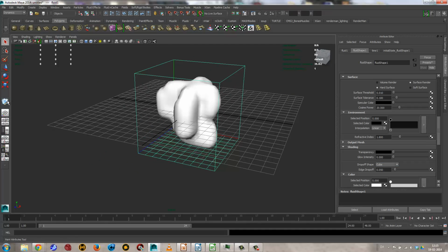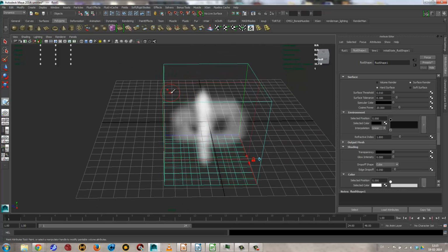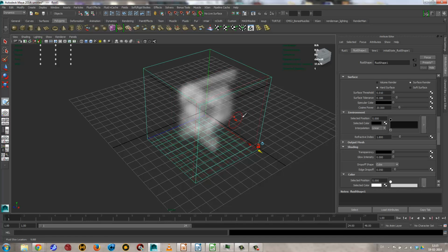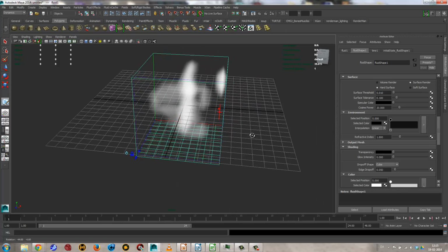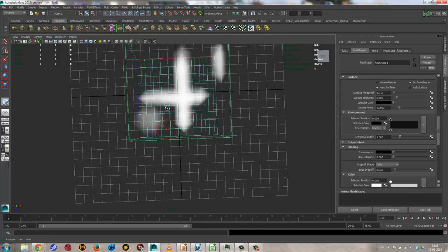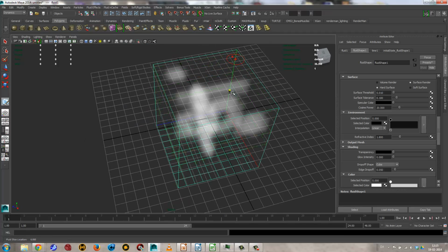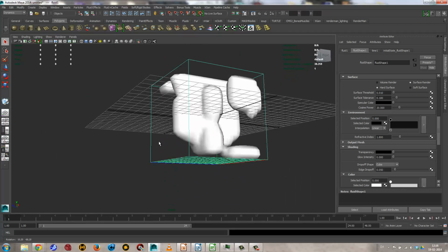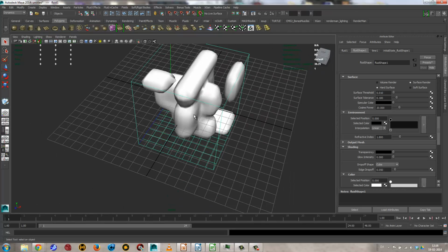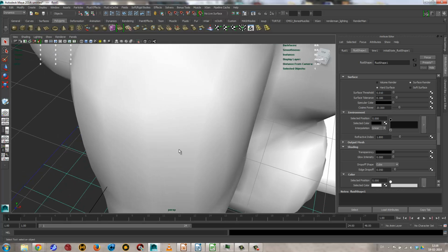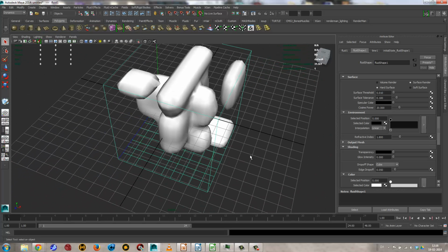So if I go back to the paint, you can see it'll paint in this ghosting mode. But I can add things and then go here and middle mouse button drag this to draw at a different point, and then maybe do it like this and add a little bit down there. Then I just drag this to the bottom and drag a little bit there, go back, and you can see this is a voxel definition. This is just the display, the boundary representation we're seeing, but actually this box will contain the information of a solid definition.